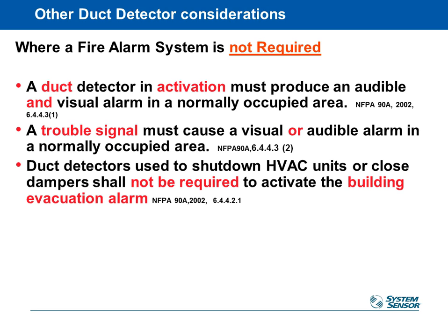You're not required to activate the building evacuation alarm. You're just required to make notification in that particular occupied space. So if rooftop number 3 trips on smoke detection, the little horn buzzer and flashing light down in zone 3 has to flash and alert the occupants, but it does not have to trigger the full building evacuation alarm for all the other buildings and floors.